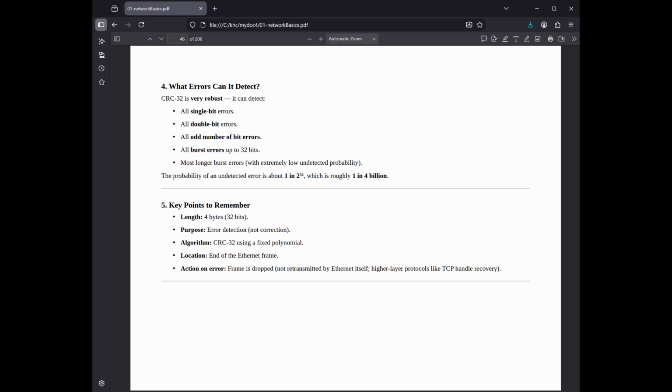3. Hamming distance: the code effectively imposes a minimum Hamming distance of 3 between any two valid code words in the Ethernet system. A code with a minimum distance of d_min can guarantee the detection of all up to d_min minus 1 errors. Since the distance is 3, it guarantees detection of 3 minus 1 equals 2 errors. In short, the mathematical structure of the chosen 33-bit cyclic generator polynomial, as defined by the IEEE 802.3 standard, ensures sufficient mathematical distance between valid data patterns to instantly identify when up to 2 bits have been flipped.